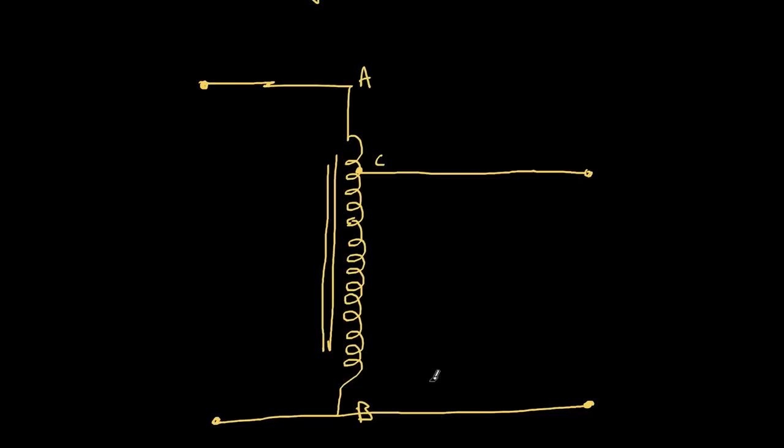What does a transformer do? A transformer transforms the voltages. So whatever voltage is here, slightly lesser voltage will come here because the number of turns are less. So for example, if I consider this entire winding, that is N1, as 1000 turns, and then this one I've just slightly reduced it, so maybe N2 is only 950 turns.